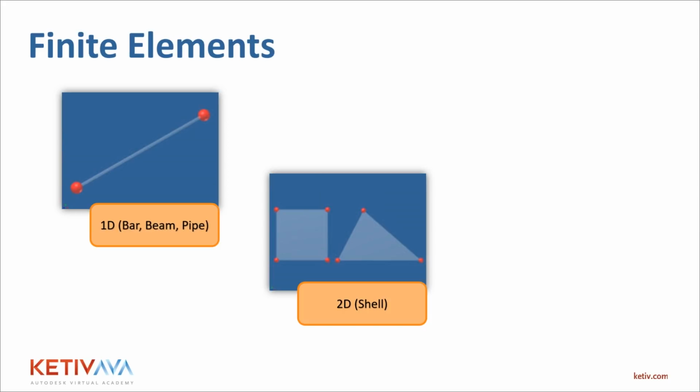2D elements are typically surface elements with triangle or quadrilateral shapes as their basic shapes anyway. These surface elements can have either regular shapes or irregular shapes in the model itself. And they're often used for 2D elasticity problems, since they account for plane stresses and plane strains. Now, the fundamental property of a shell element is the actual thickness. You can assign this thickness property to geometric surfaces or geometric solids, depending on what your model requires.